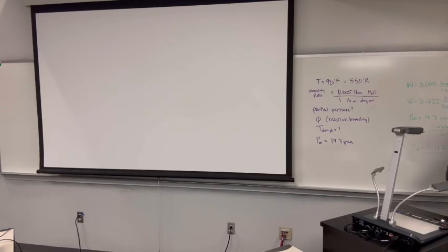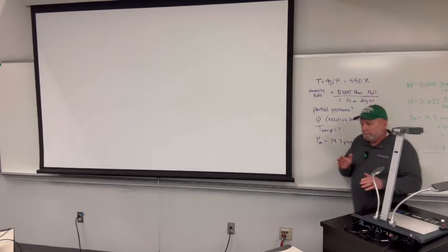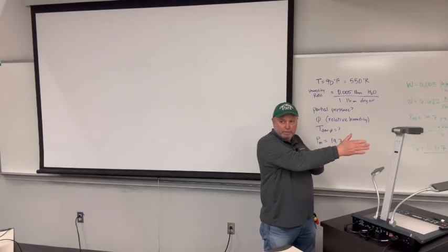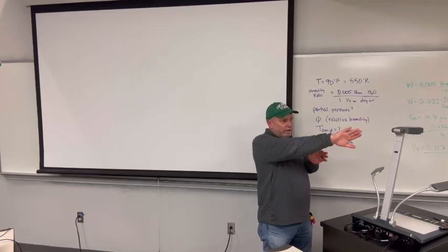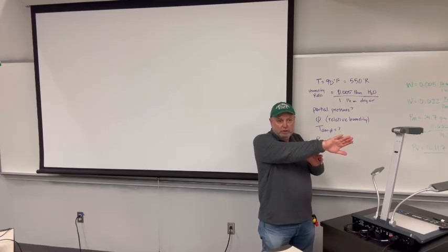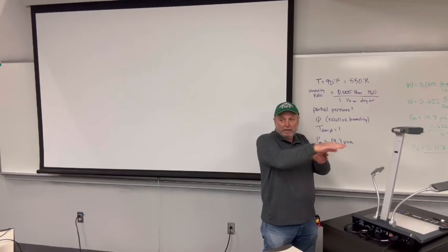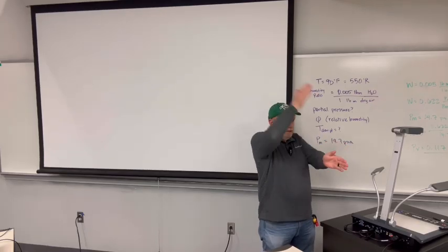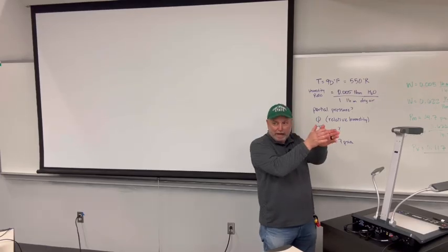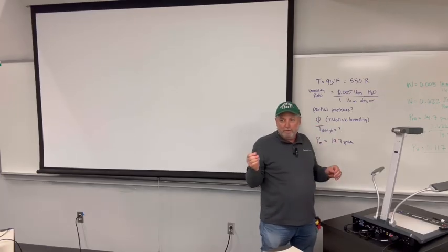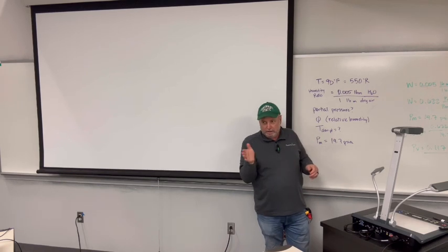So if you think of this, you sight your back sight, you set your 0 angle, you measure. When you flop the scope and you turn back to your back sight, you should read 180 degrees as your back sight. Because think about this, this is 0. Right behind me would be 180. So when I flop my scope and look back, I should be close to 180. Probably going to be off a few seconds, give or take.